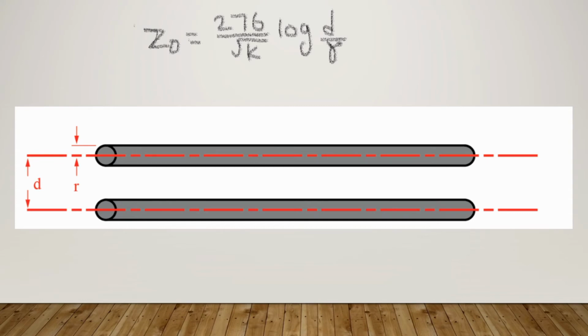So what happens at the end? Finally, in the infinite transmission line, the wires are infinitely long, so the distributed capacitance will never get fully charged to the source voltage, and the distributed inductance will never allow unlimited charging current. In other words, this pair of wires will draw current from the source as long as the switch is closed, behaving as a constant load.